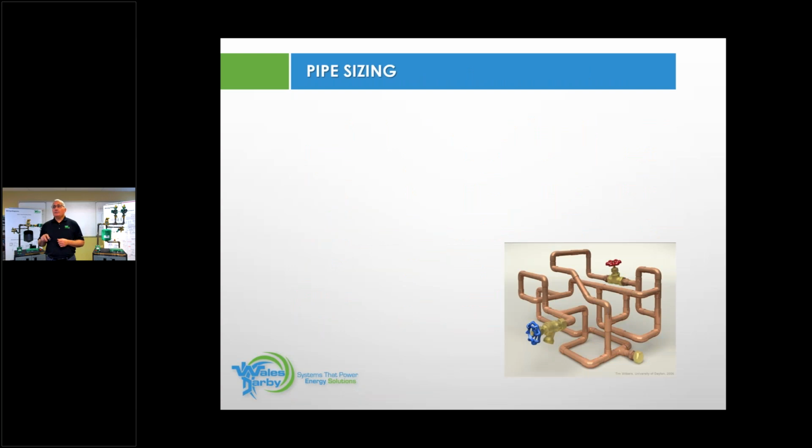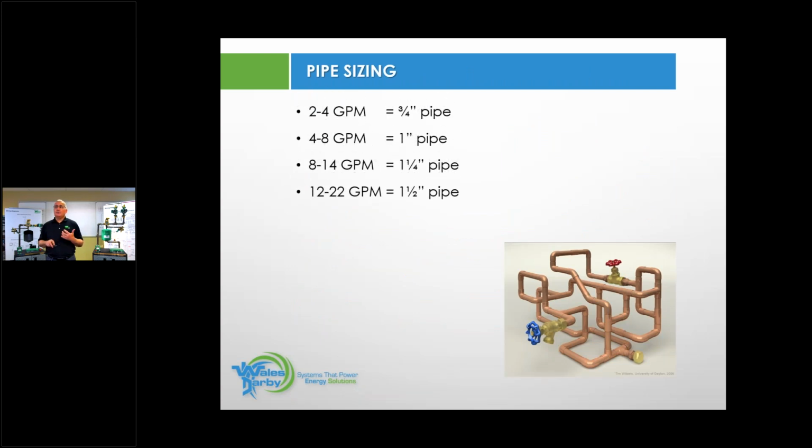All right. Pipe sizing, again, this is in your take-off handout. These are the GPMs for 3/4 through 1.5 inches, as you can see here, to make sure we stay within that 2 to 4 feet per second, so we don't cause noise, we don't cause any erosion. Everybody should remember when we were talking about air, John talked about getting air out, right? We definitely want to make sure we're not any slower than 2 feet per second. Otherwise, bubbles get big, fat, and happy, belligerent, and they could cause a problem.